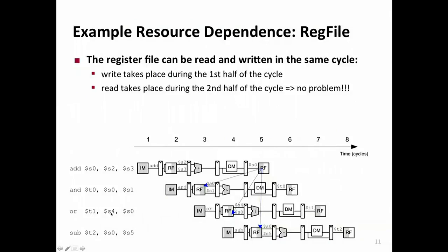So if you look at this instruction, this OR over here, this OR needs the result of this add again. And we don't want to wait until the add writes to the register file, because OR gets to the register file stage in cycle 4. Well, how do you get the result? Well, add is in the memory stage, and we know the result, because we produce the result and we're just carrying it with it to write to the register file. So why don't we forward from this stage to this stage? So you need to have another forwarding path.